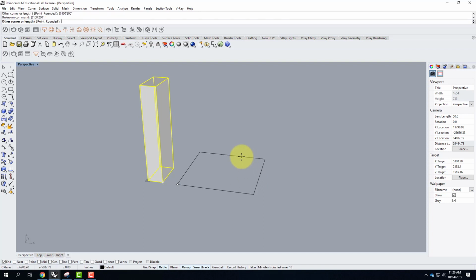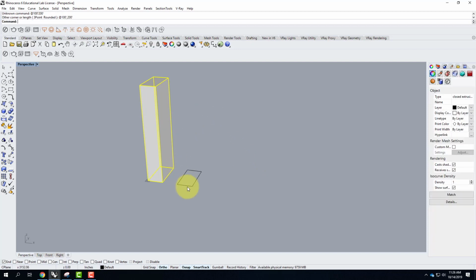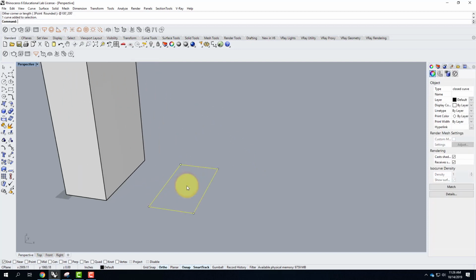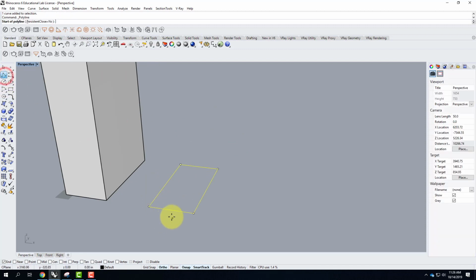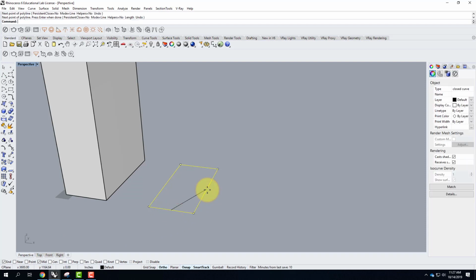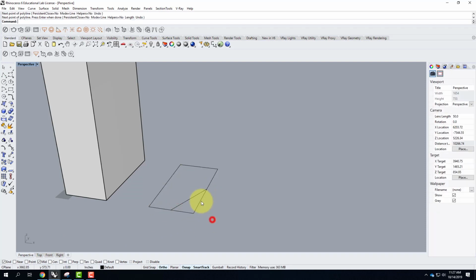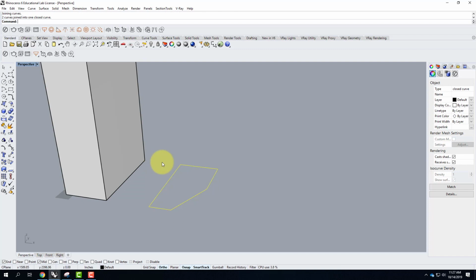Oh, I forgot a comma there. And I'm going to look at this and say, okay, what if I cut off one of the sides? So let me turn on my midpoint snap. Let's say I cut that side like that and I clipped it. We'll trim that piece off, and then I'll take these and join them together.